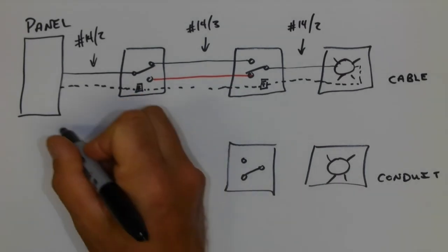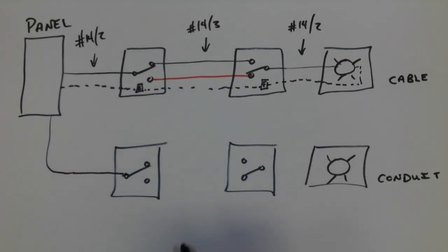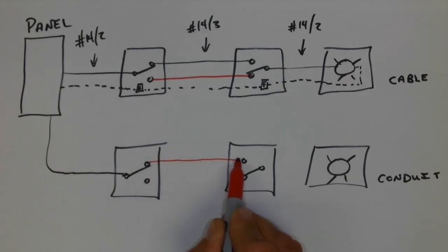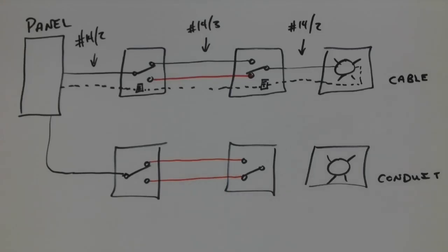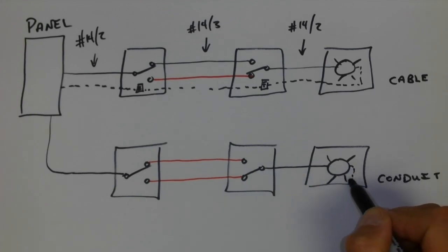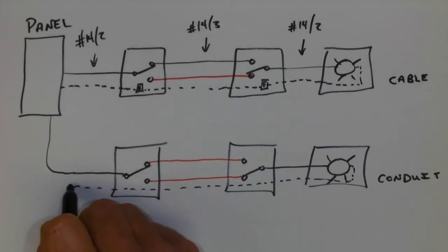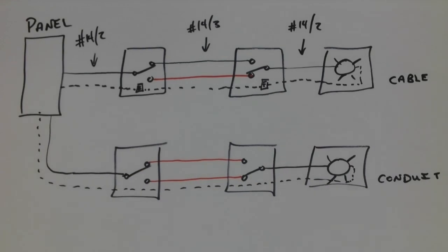Again, in the conduit installation, we have a black conductor coming all the way into the common. We would have two separate travelers, and the coloring is really up to the installer. It doesn't matter, it just can't be green or white. And then again, black conductor, and this time the white continues all the way back uninterrupted until it is connected to the neutral bar. Now, the legacy equivalent of this is again a form of a dead-end switch.